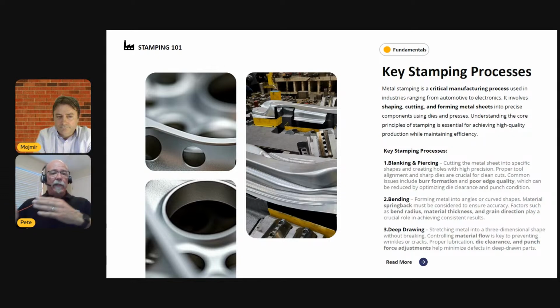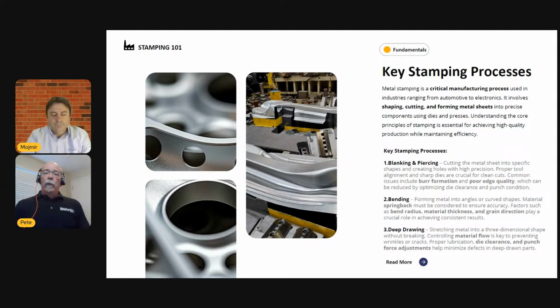If you have to make any adjustments in the die, including stencils, you need to shim the stencil up and down. Now, the only exception, if you're adjusting for stencil depth, would be a blanking die, or just a die that's doing cutting, because you have no stations that are hitting home. So if you're not hitting home on the material in the die, you do have some flexibility to make shut height adjustments for those forming depths.